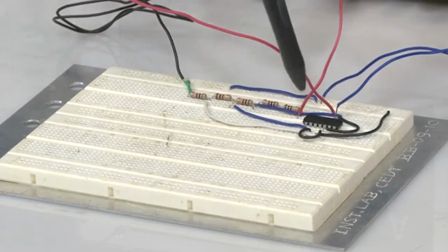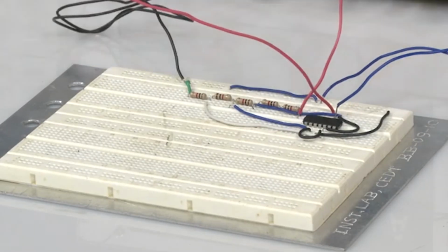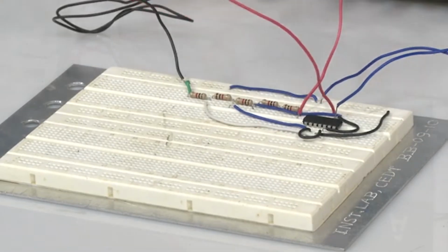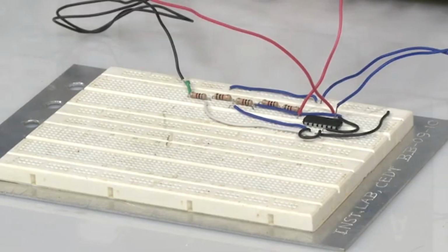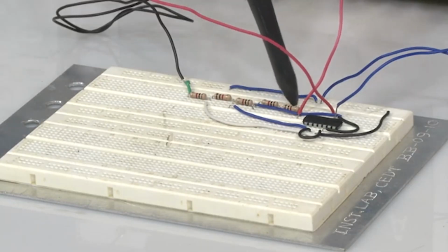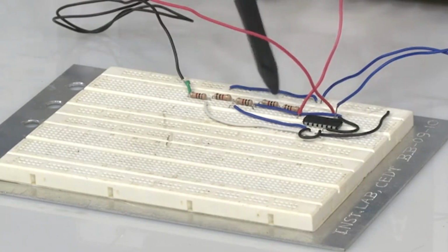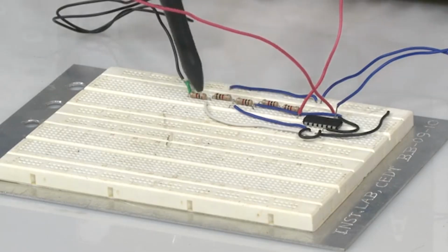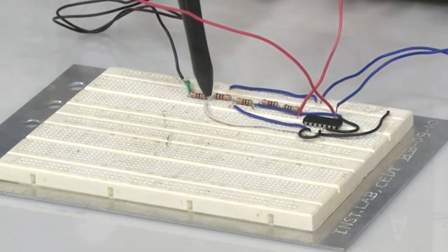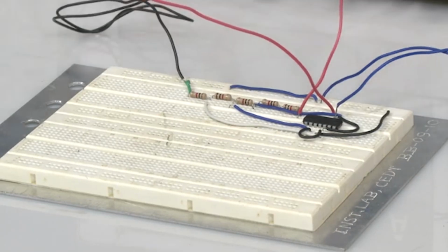That is why the negative terminal is connected to the ground, and the positive we are connecting to plus VCC, which is nothing but 5 volts in this case. And these are the other resistors, starting from 2K. So this is 2K, 1K and 1K in series, 2K, and another set of resistors 1K, 1K, 1K. The output we take at this point is nothing but VC.